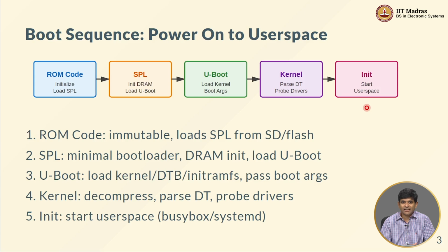What is usually done at that point is we introduce a new special signal called a reset signal, which, using some kind of very simple electronic circuits, probably even just an RC delay or something like that, we make sure that the reset signal is held at a certain value for a certain amount of time. Now, the good news is all our flip-flops have the ability that if I give them a reset signal, I can force them to either a 0 or a 1, a known state, in other words, right, that overrides the clock signal.